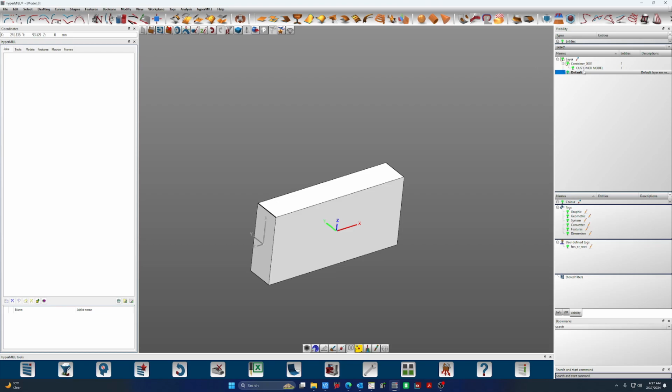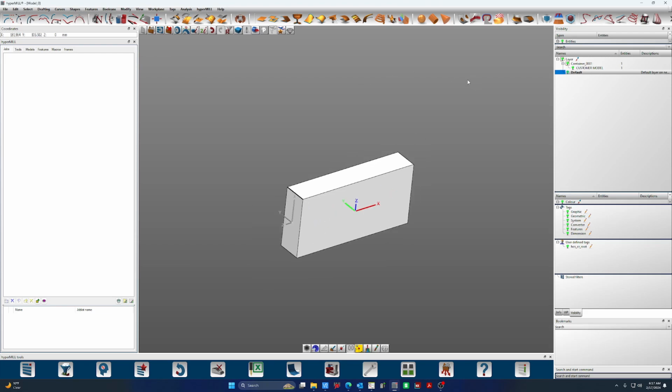If we would like to make another layer the de facto layer for whatever we're doing, whether it's creating geometry or surfaces or duplicating a solid, we just double click that. You're going to see that it becomes emboldened, and that lets you know that is the de facto active layer. So that's kind of the layering tool.